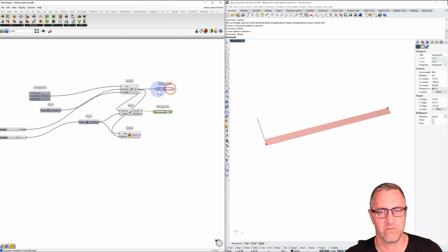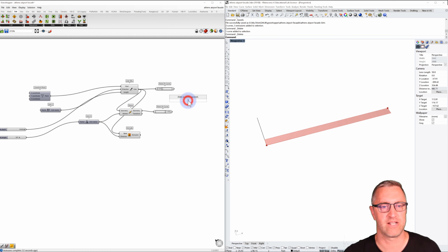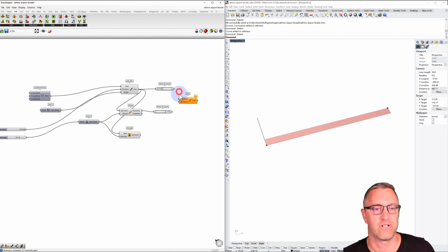I think really where I want to do this is have this along the front edge when the panels are flat, and then move to the back when the panel is open. And so once I have that, let's create a line between them. And this will be between 2 points. Our start point is on the left, and our end point is on the right. And so now we can see the way that that line will also shift along its length.